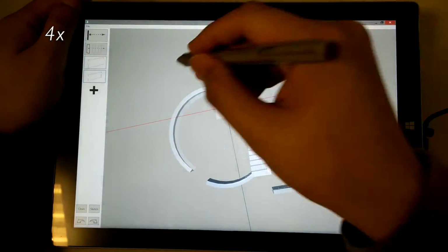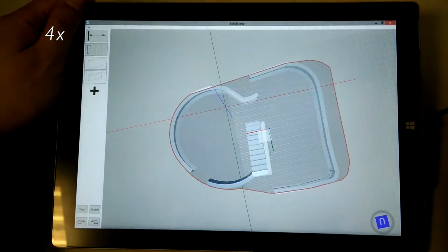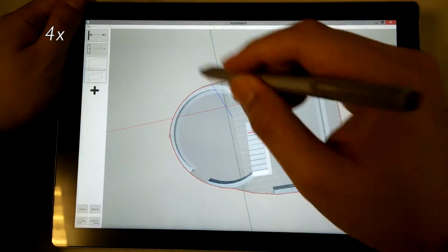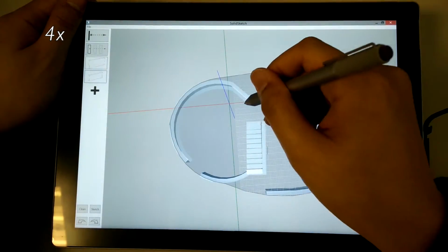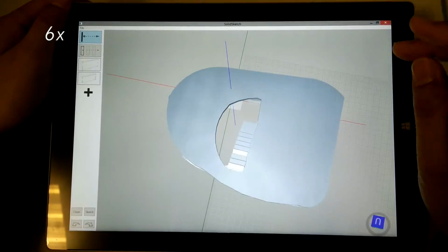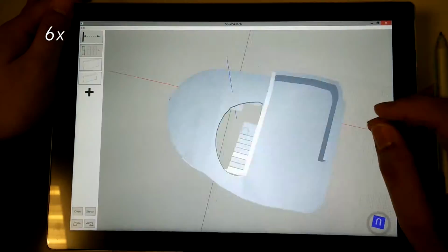Similarly, after the user moves the grid plane on top of the wall, the user can draw and modify the slab of the second floor. Creating a skylight in the house is simple. Drawing directly inside an existing polygon will create a hole in that polygon. After the slab is finished, we can draw a wall right on the slab using the same template we made earlier.